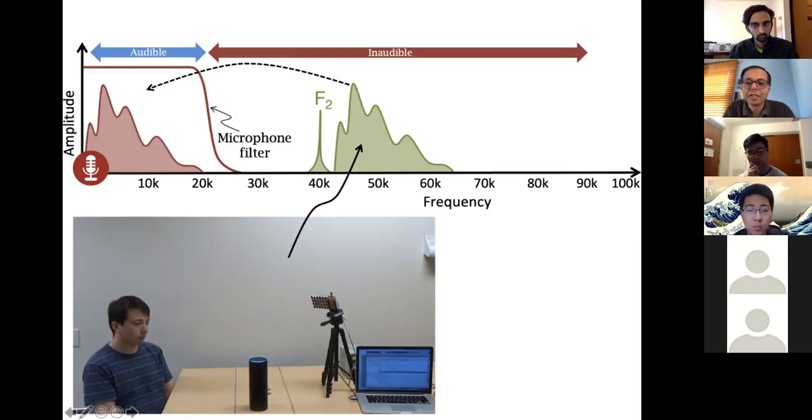So what we really did over here is that this green signal is the human voice signal, what is the capital city of United States, but then pushed to a high frequency to 50 kilohertz as the center frequency. Okay, it's the same voice. Now, when you play that signal, which is the same voice pushed to 50 kilohertz, it is inaudible to humans, but through the microphone that gets shifted back. Right? So the laptop is essentially playing this green signal.